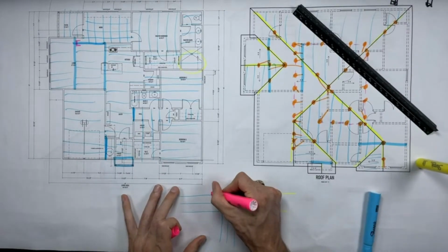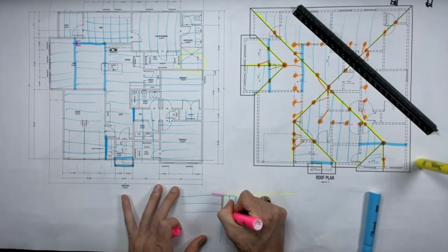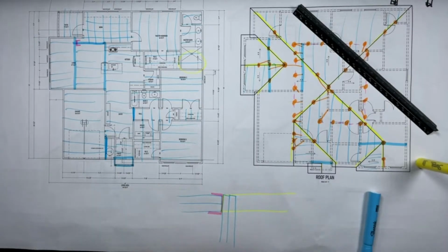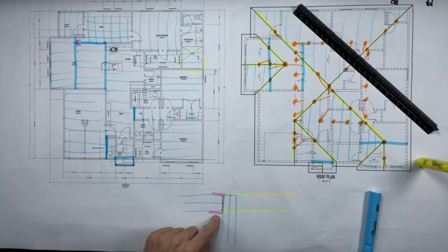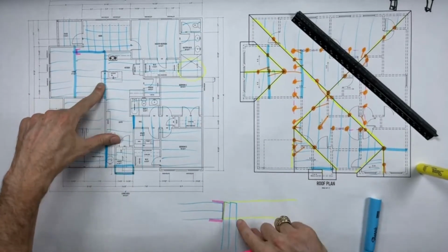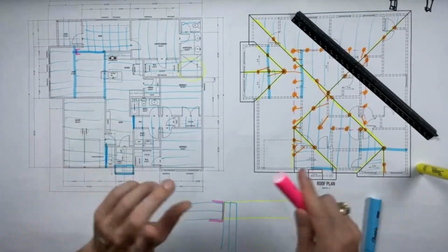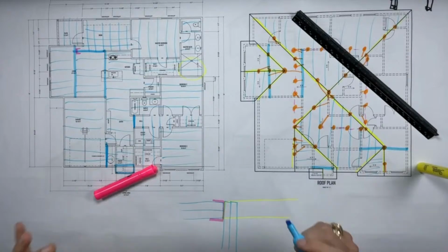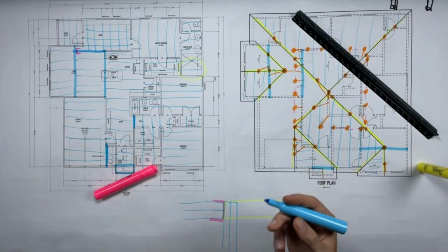Okay, so if I do this, I've got a hanger. Now, I would have to use a concealed flange hanger to do this, because I don't have any wood over here if I cut this beam right to the length of the wall. But most people don't cut the beam short if they don't have to, because that's just extra work.